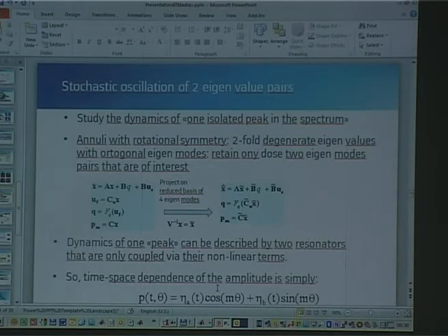So we have gone from a model of the order of hundreds to a fourth order model. And this fourth order model is nothing else than two coupled linear oscillators. And it turns out that the coupling of these 2 oscillators only occurs via the nonlinear elements in our system, if the system is completely symmetric.